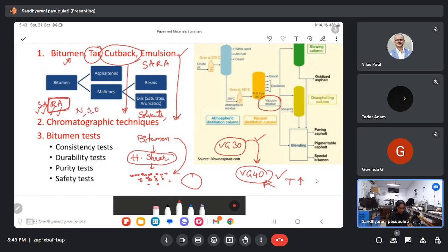So, what is the use of that? If they have these, actually they can react with anything else, with each other. Like resins to asphaltenes also they can react. So they are not like inert materials. They can react with environmental products. They can react within themselves. If I am going to add some polymer from outside to increase its properties, still they can react with them. But saturates and aromatics, these are actually non-polar materials. They do not have heteroatoms like this, so they will not be reacting.